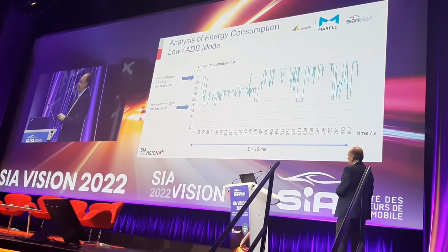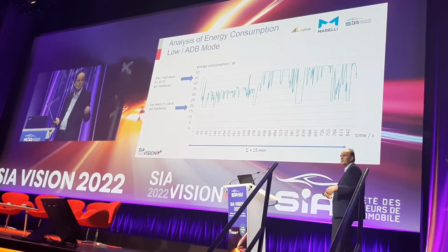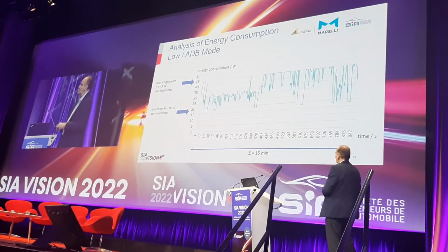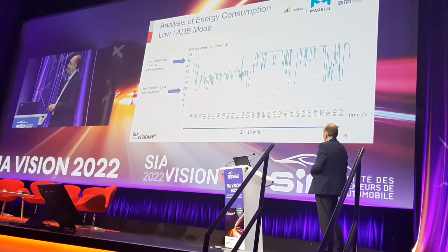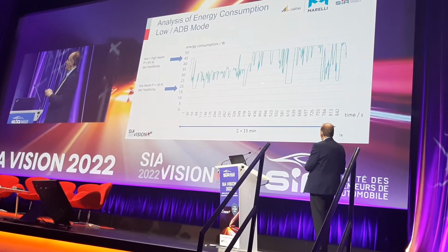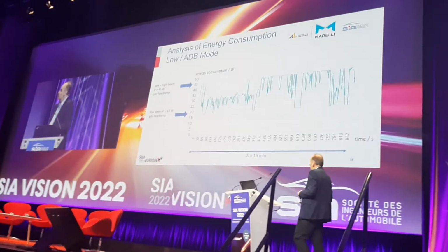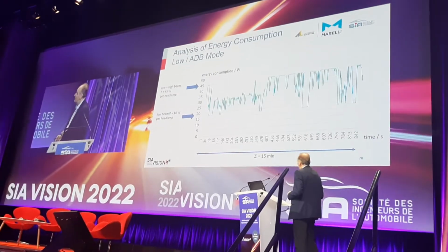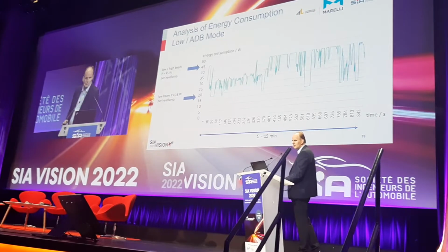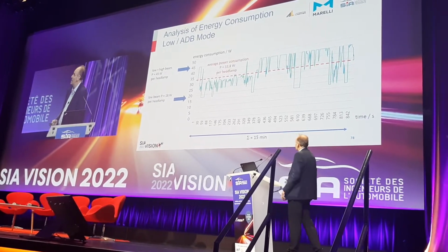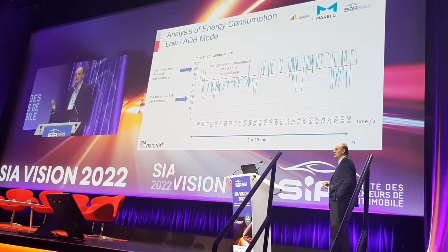So we see that the power consumption here is moving and is very dynamic, even when there is a car in front of us, because the segments right and left are switched on. And even in the situation where oncoming traffic exists, we only come back for a few moments to the low beam power consumption. Another question is, what is the average for this light distribution in this section? You see it here: 33 watt is the power consumption of this ADB system.